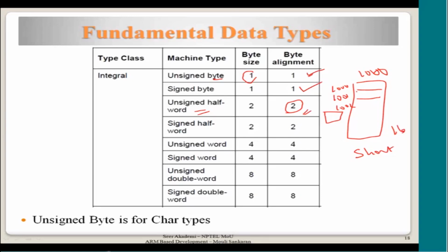Then we can store it in half byte boundaries. It could be signed or unsigned. Normally we can write it as unsigned or signed in the C language. Based on what we choose, it will be interpreted internally. As I explained a long time back, the generated instruction will look at the overflow flag or the carry flag based on what type of variable is being looked into.